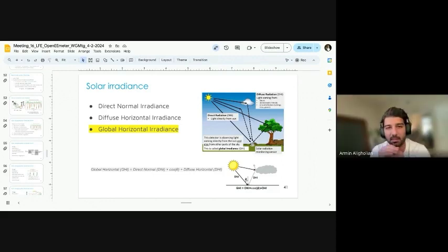Yes, 100%. That's exactly why we don't define extra restrictions for the model and let the meter data itself decide what the model coefficients should be. If we consistently have a cutoff in the middle of the day, then the model should learn that pattern from the training set, and hopefully we have the same pattern in the test set, because we're just looking at the covariates, which are temperature and GHI. If that's the case in the training set and we train the model to learn that, we should be able to see it on the other side, which is the test set or reporting year.